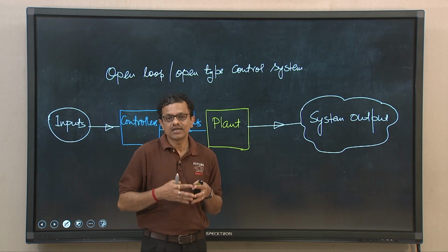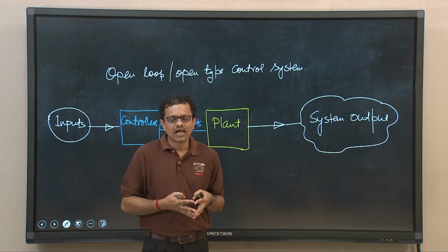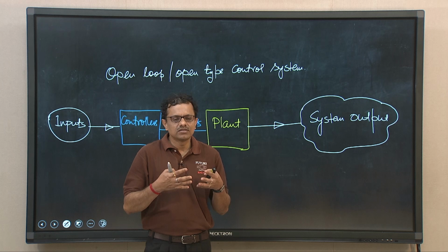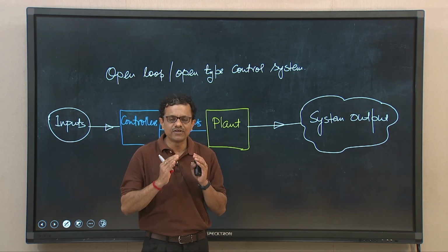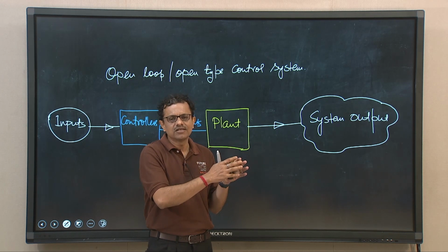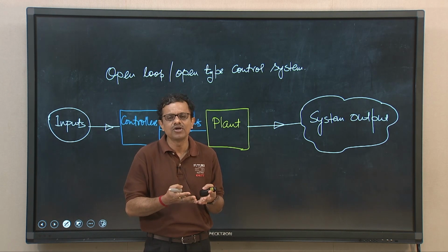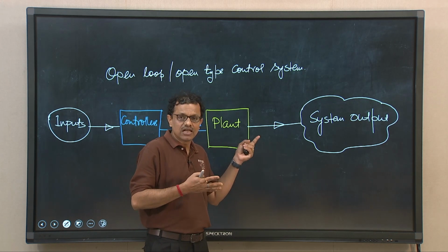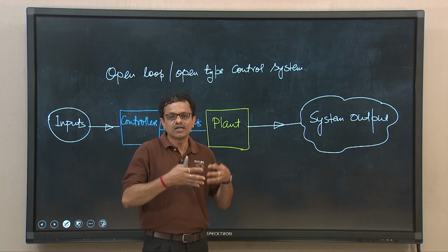Now, if the car needs to go uphill, then certainly it will decelerate, engine speed will reduce, and the electronic control unit or electronic engine management system should provide some feedback to the throttle valve or sensor in the fuel injection system to supply an additional amount of air fuel mixture, so that more torque will be developed. But that feedback is not there. Due to the lack of this feedback, these systems are not used or can be used under certain operating conditions only.